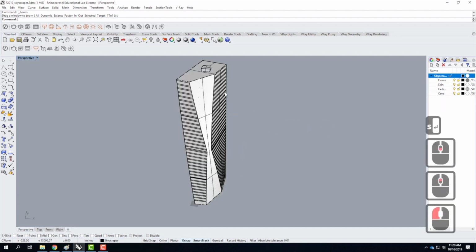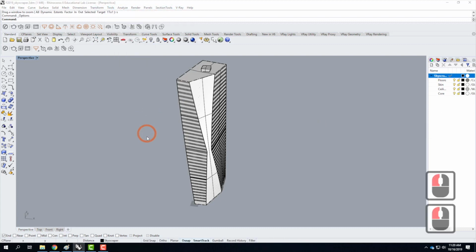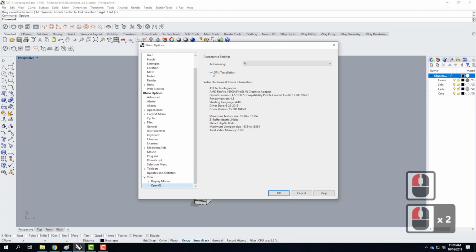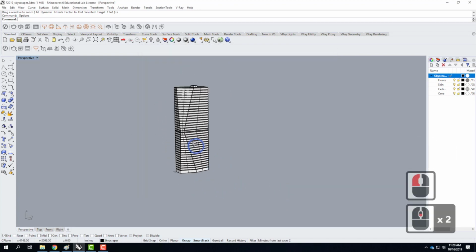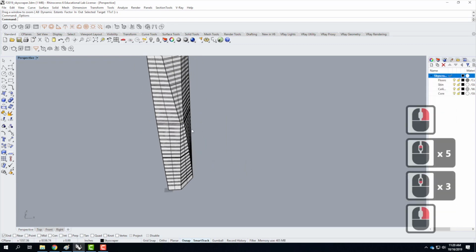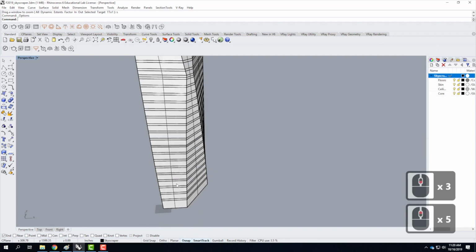I have not turned off my OpenGL just yet, so that's going to be problematic. Let me go ahead and do that. I'm going to go to Tools and then Options, and under View, I'll click on OpenGL and turn off that GPU tessellation, and that'll let me see my building correctly. So now I have my building. It's on 0, 0, 0, and it's time to double check my various materials to make sure they're applying correctly and at an appropriate scale for the building.